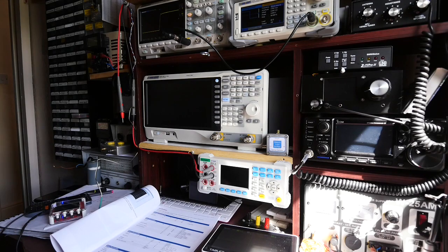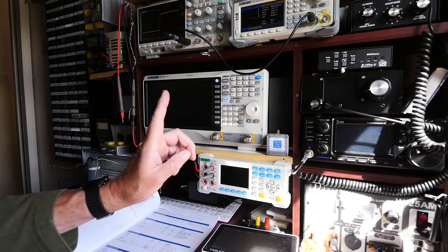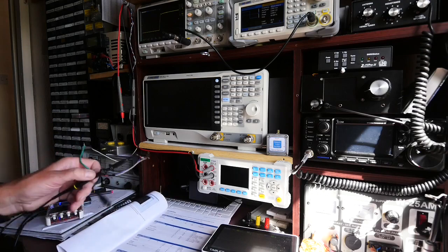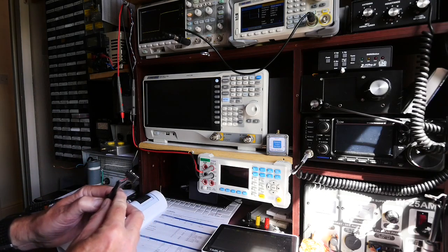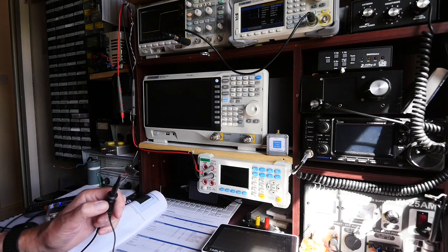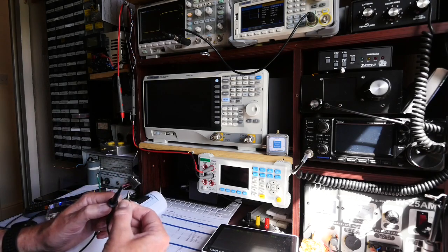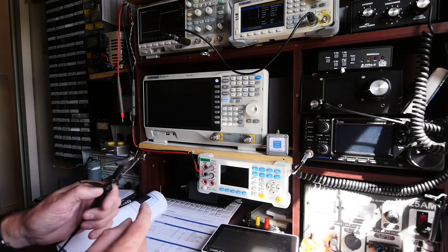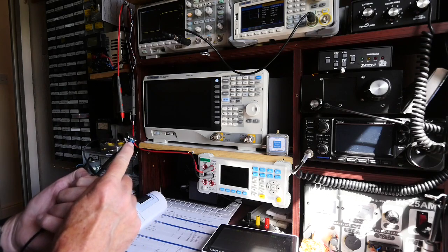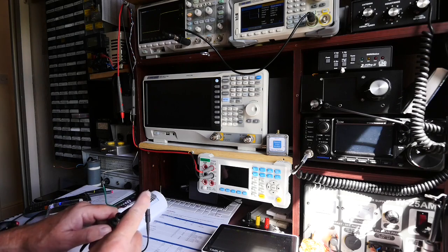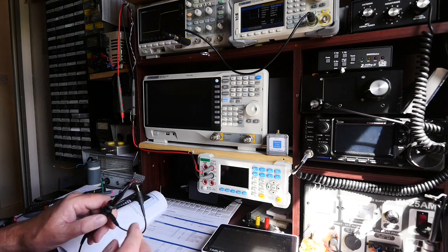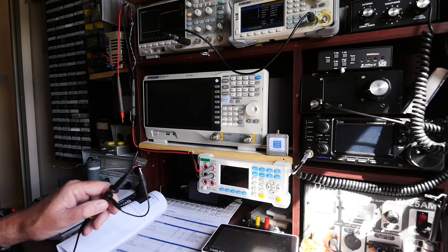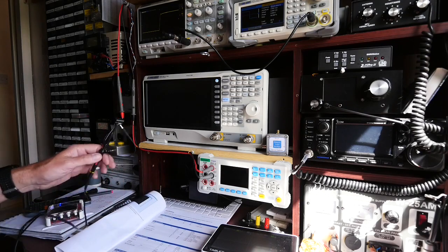Alan Walk's video, W2AW, I'll put a link at the top of the screen for you to go to, he produced a Schmitt trigger oscillator using the SN74AC14, which is the advanced CMOS chip. It's quite fast. It's a very minimalistic design here, trying to keep the leads as short as possible. So I've got the chip running there with a capacitor and a resistor to give me the Schmitt trigger oscillator. And Alan is of the opinion that the rise time of this circuit is about 2 nanoseconds.